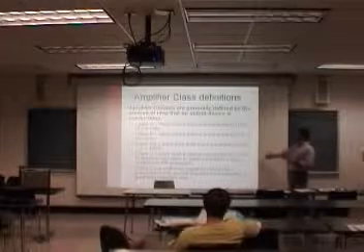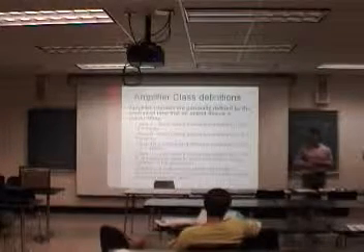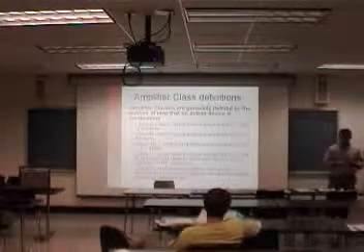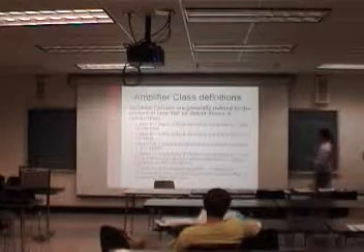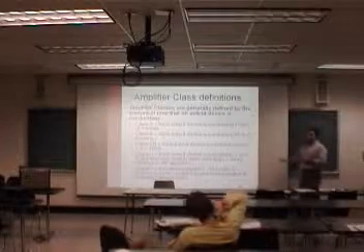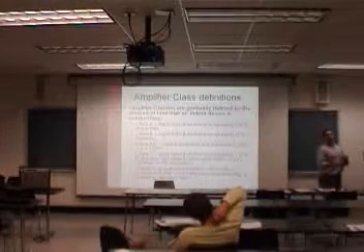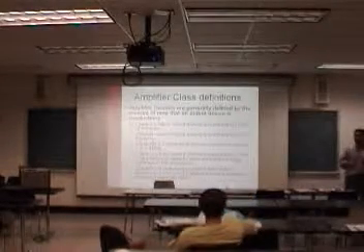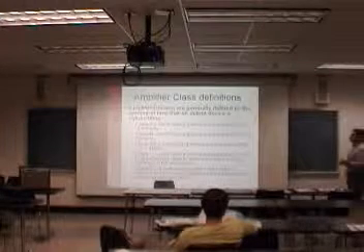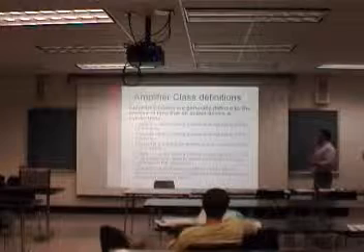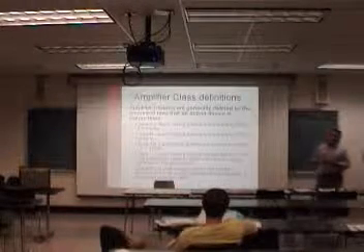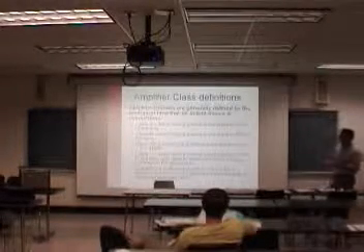Class C is something I'd like to mention, although I don't think I've ever seen it used for audio. Class C means the output is conducting less than 50%. It's a pulse amplifier. It's an efficient amplifier, and it's often used in radio in conjunction with a tuned tank output. But it's not worthwhile for audio because it's just too distorted.